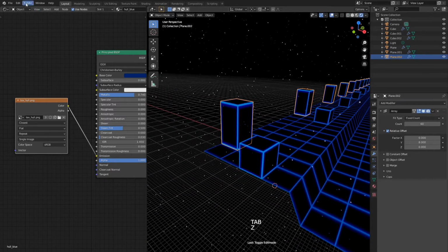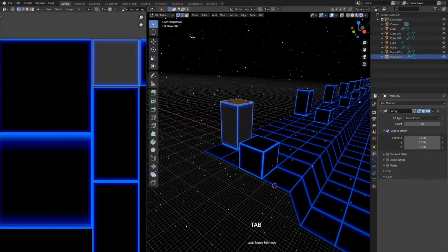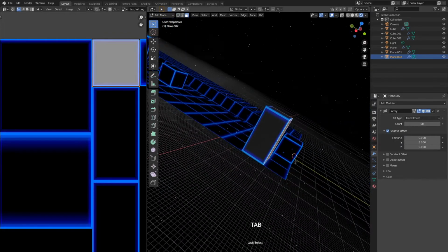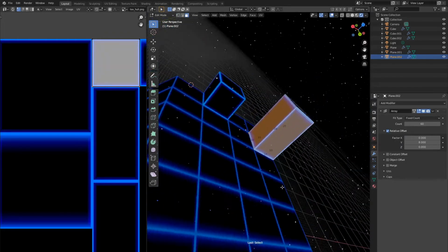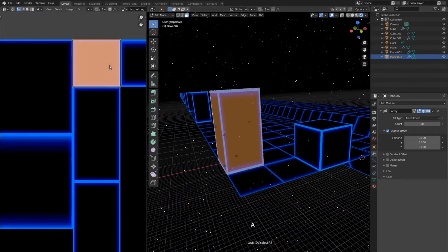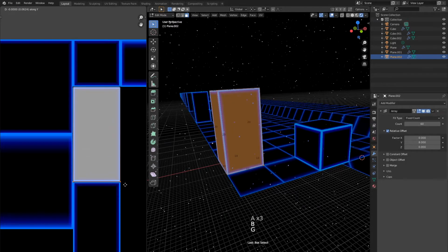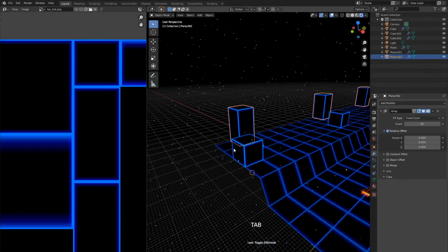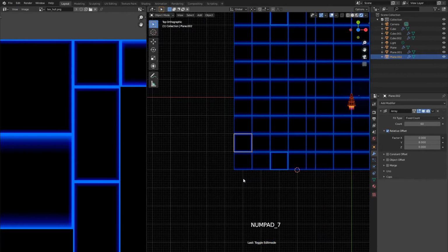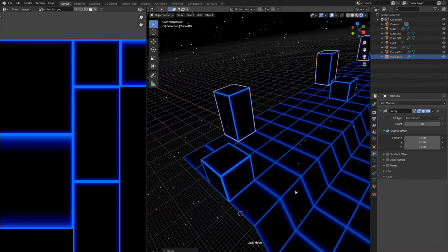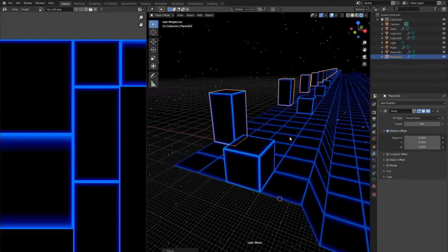Now go back to the UV editor to fix texture stretching on sides of the cube. Select all 4 faces and let's check if they are properly aligned on the UV layout. Okay, we need to rotate them 90 degrees. Now remap them to a rectangle we have right here. Just like that. Looks nice and tidy now. Let's move it 2 grid cells forward so we have some variation between buildings. Change count value to 80 so they are visible from even greater distance.